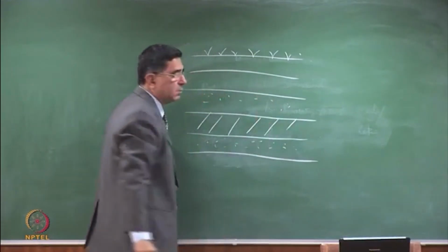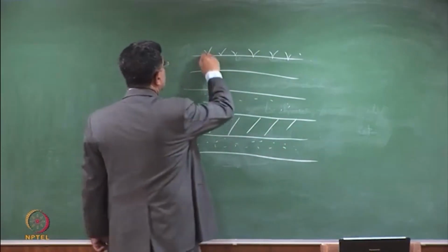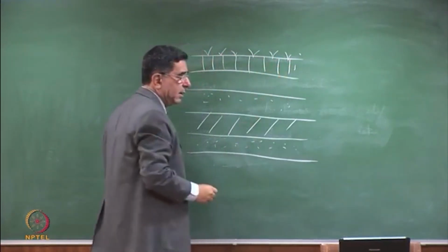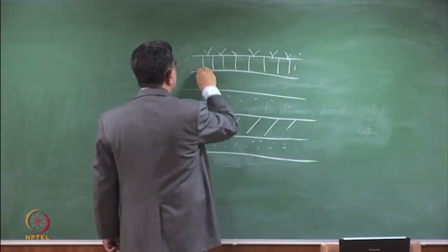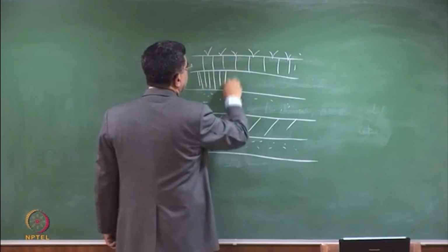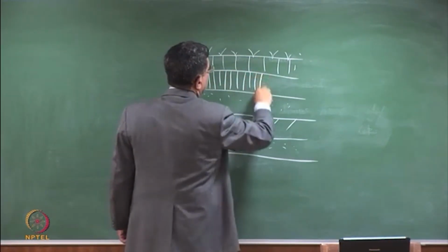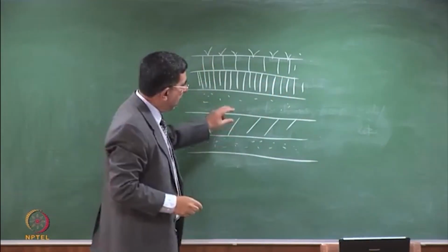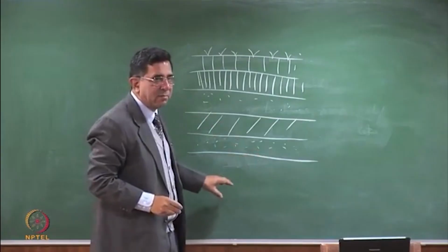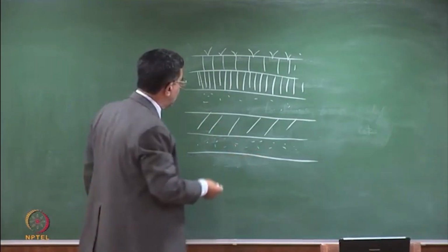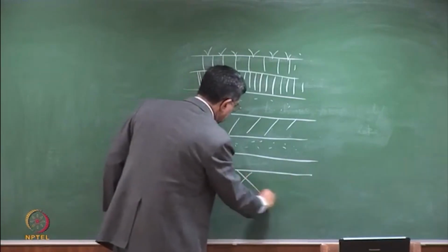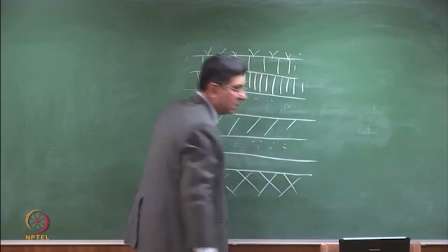And I'm just putting a municipal solid waste cover. So this is the topsoil in which your vegetation will grow, right? This is the protector layer, drainage layer, barrier, gas collection layer, and a foundation layer if you need one. And then the wastes. You all remember this?